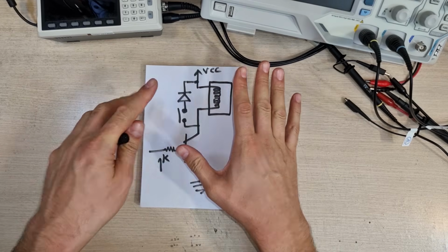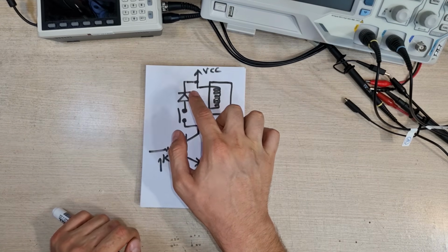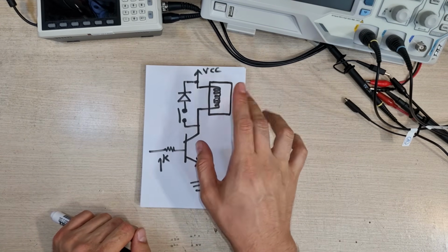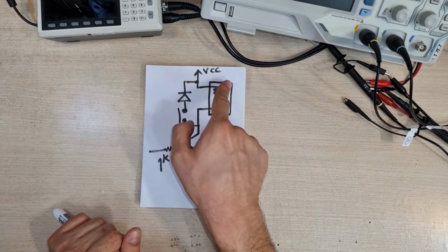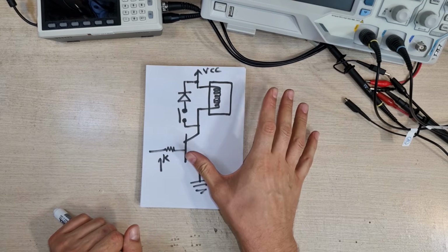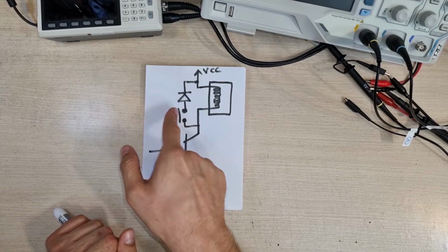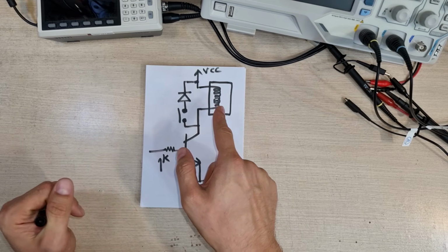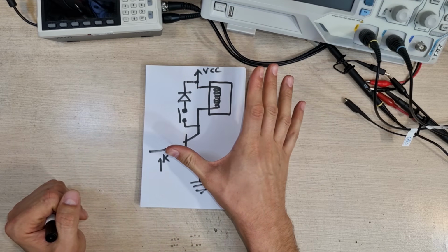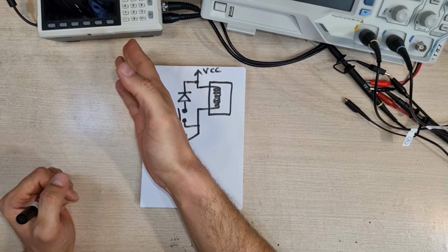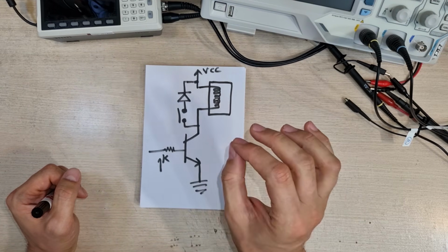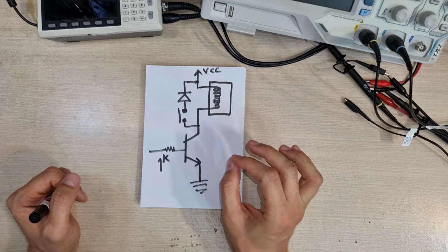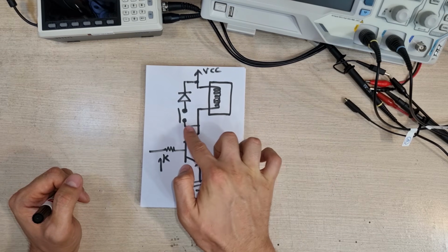Look here, one flywheel diode stands beside each relay and is connected to it in parallel. The cathode pin of the diode is toward VCC. In this circuit, I am using a tactile switch to connect or disconnect the diode to see its impact. I am going to use my function generator to turn the relay on or off 5 times per second and use my oscilloscope to see what is happening at the collector pin of the transistor here.